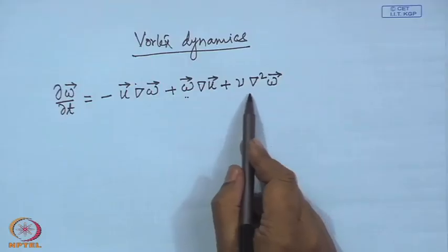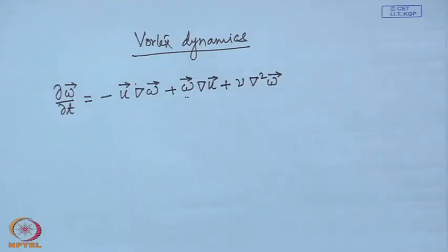But perhaps that itself is not sufficient to answer how the vorticity comes in the first place in the interior of a fluid which is moving uniformly. When the fluid is moving uniformly, there is no vorticity. This viscous diffusive action can spread vorticity once it is there, so it still does not answer how it comes.